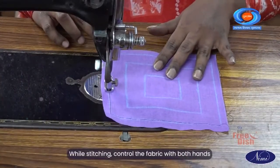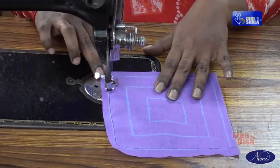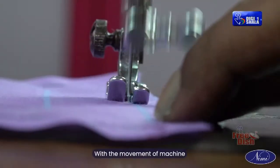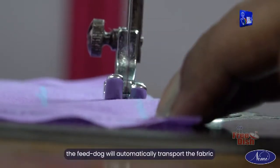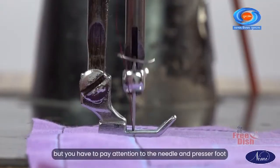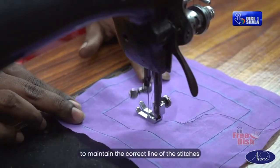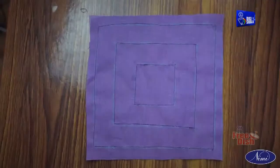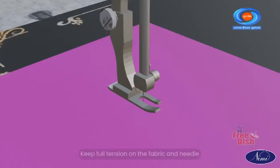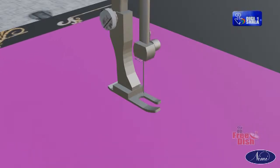While stitching, control the fabric with both hands. With the movement of the machine, the feed dog will automatically transport the fabric, but you have to pay attention to the needle and presser foot to maintain the correct line of the stitches. Keep full tension on the fabric and needle.